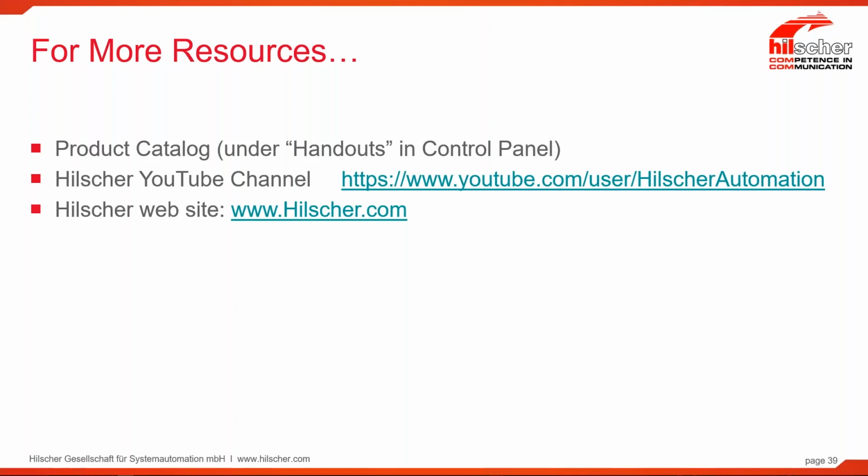And the answer is no, but it depends. Again, as I mentioned during the presentation, the gateway hardware itself is only limited by the actual connector that is there. So, for instance, if one side needs to be Profibus, you have to order one that has a Profibus connector on there. If the other side's a Profinet, you just order one with an RJ45, and then at that point it becomes unlimited.